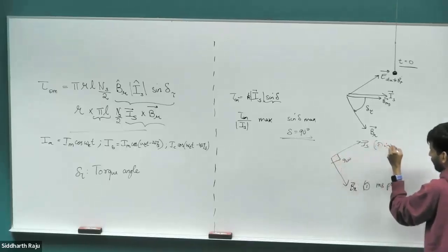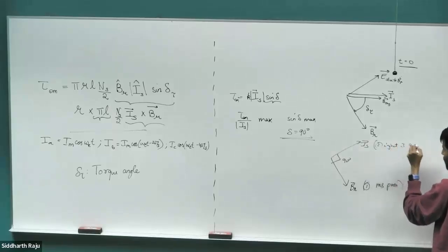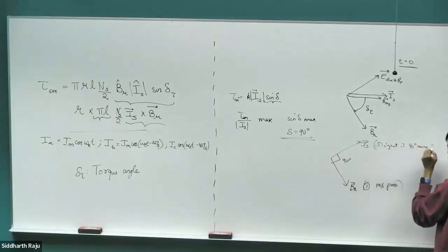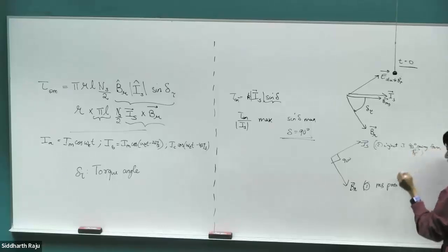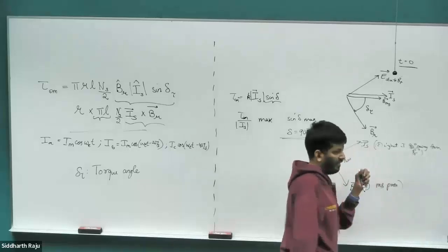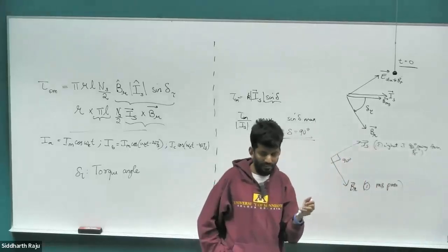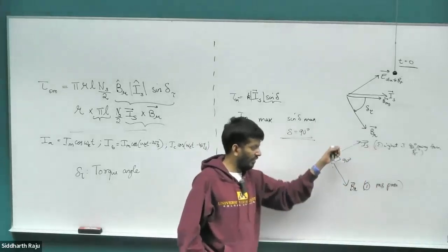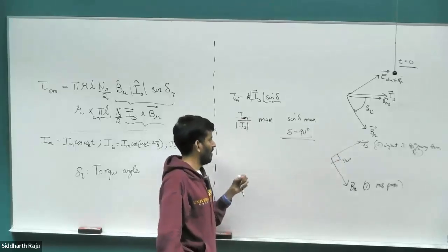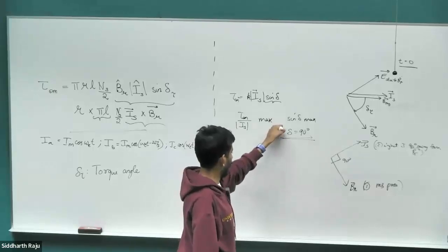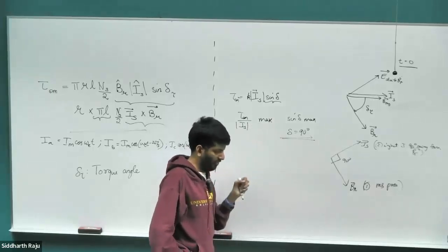So inject IV 90 degrees away from the DR space vector position. The way we would inject that is to create three currents in the stator such that the space vector ends up being 90 degrees forward. It's a little bit of a trivial math problem to solve and figure out what those values are. So this is what we are going to do to ensure that the drive is running at its maximum efficiency.